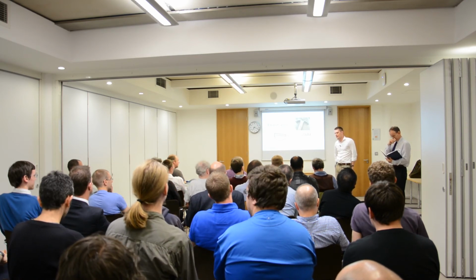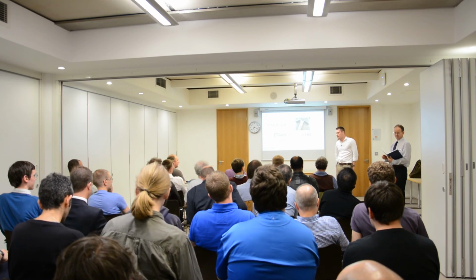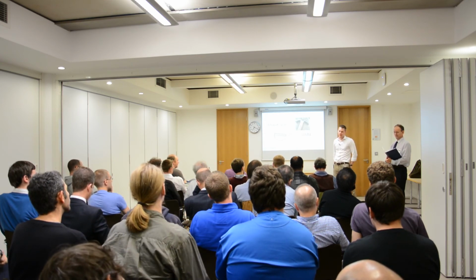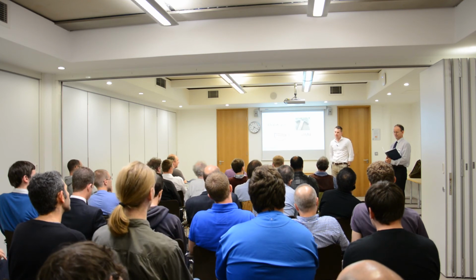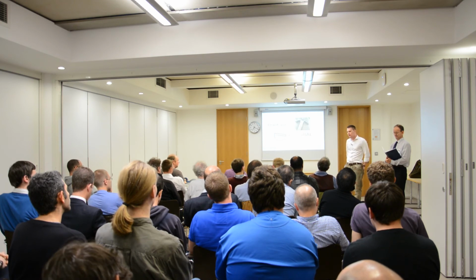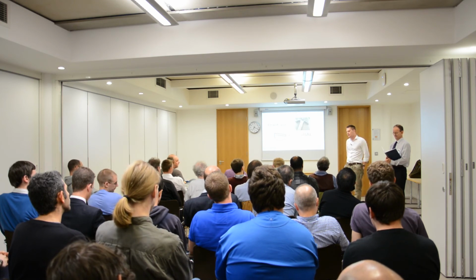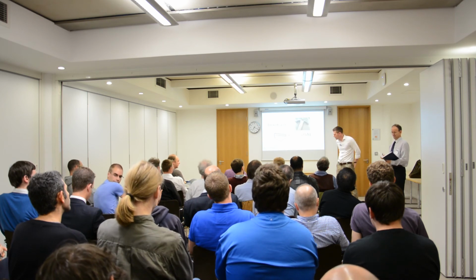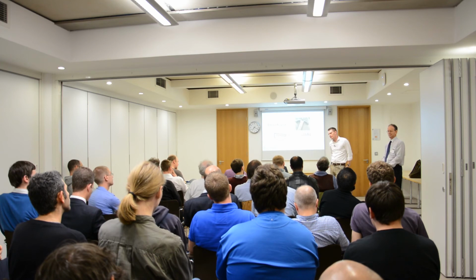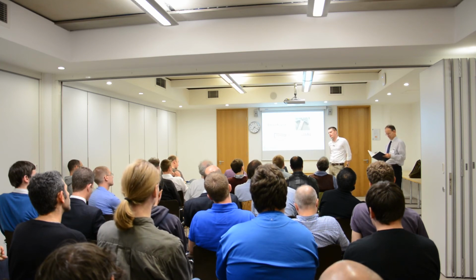It's very slow. Generally, if you're doing pipeline DSP type applications where it's numbers in, numbers out, and you've got some kind of algorithm in the middle, that works very well. If you're doing something stateful, it's quite hard. For example, if it's stateful packet processing, you can use elements of high-level synthesis, for example, to compile a DFA table or something.